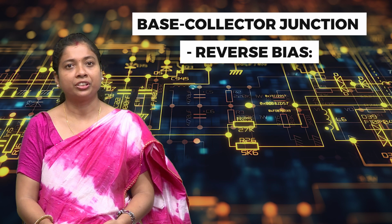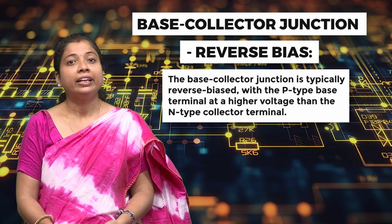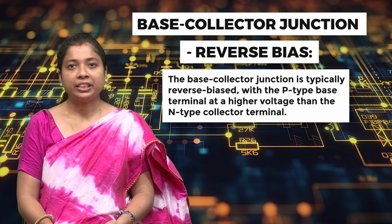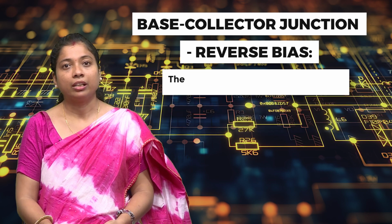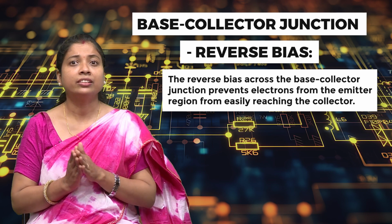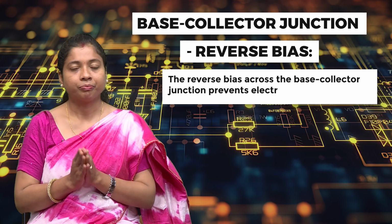The second one is the base-collector junction in reverse bias. The base-collector junction mainly works in reverse bias, with the p-type base terminal at a higher voltage than the n-type collector terminal. The reverse bias across the base-collector junction prevents the electrons from easily reaching the collector.